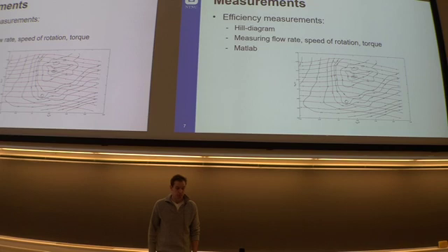We measured, among other things, flow rate, speed of rotation and torque in order to calculate the efficiency. We used these values in a MATLAB script, and it produced this hill diagram as you see here.